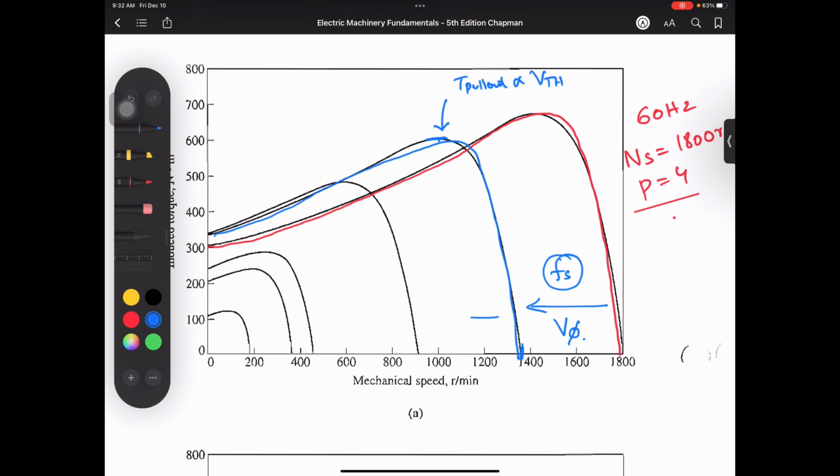And if you continue to decrease this, you see all the curves are going down. So you can see when you are designing a machine, you have to tell the user of that machine what the maximum torque is that you can take out when you decrease the frequency. Now, when you go into the industry, many of you will be in the motor industry somewhere.